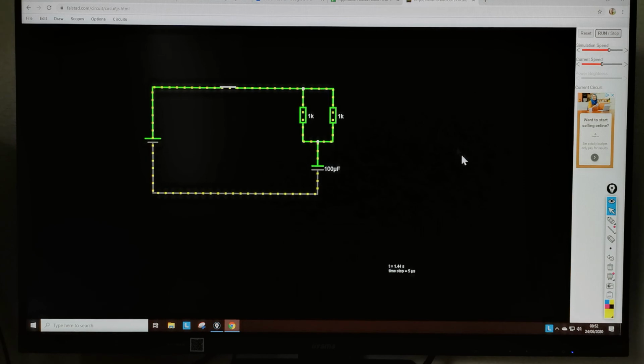So do be careful about this when you're building your circuits. The most common problem if a circuit looks correct but isn't working is that there's a red dot somewhere highlighting the fact that you think it's a connection but it isn't.